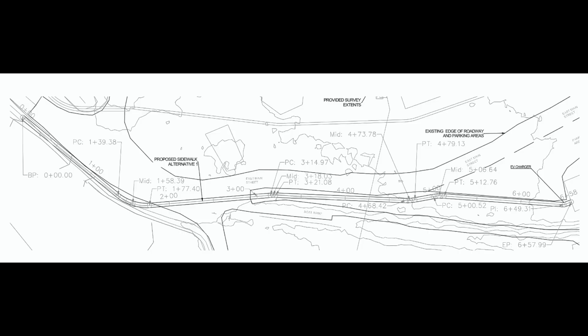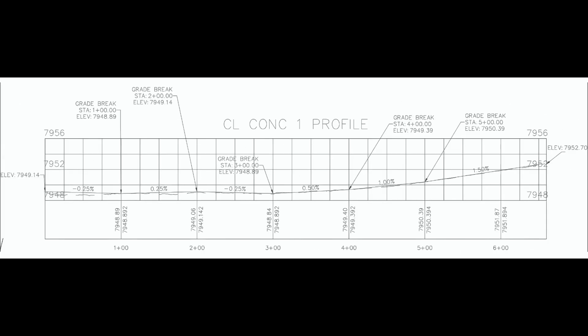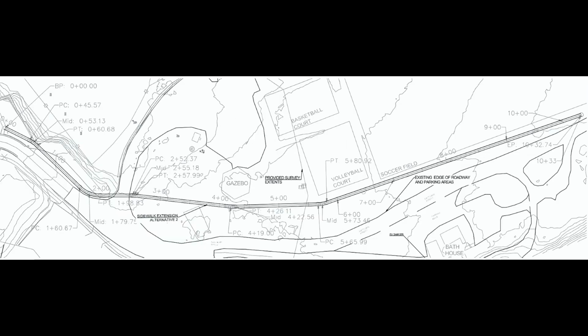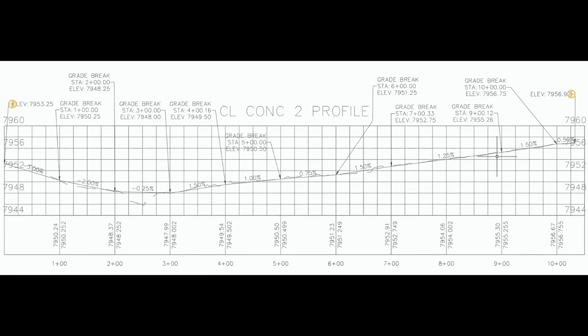Both designs are within all applicable county, state, and federal design standards for sidewalks. We used high-resolution LiDAR data to ensure slopes comply with ADA standards, providing a safe and inclusive experience. We will use 5-inch concrete for the sidewalk, given the expected loading.